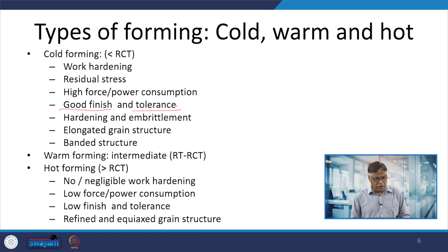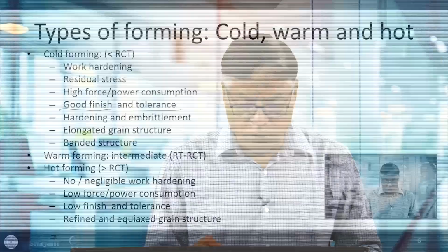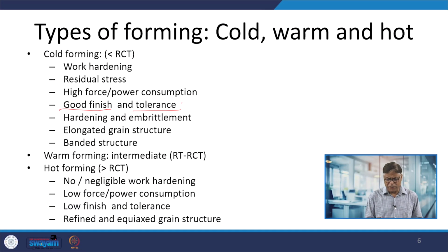In hot forming, when material is heated, there is expansion, then the material is deformed, and after the deformation it is cooled, which leads to shrinkage. This heating-linked expansion and cooling-linked contraction makes dimensional control very difficult, and that is why, when cold forming is done, control over the tolerance is much better as compared to hot forming.